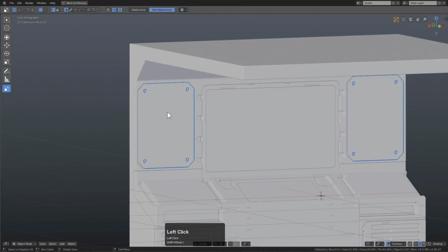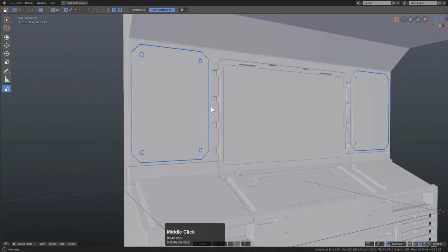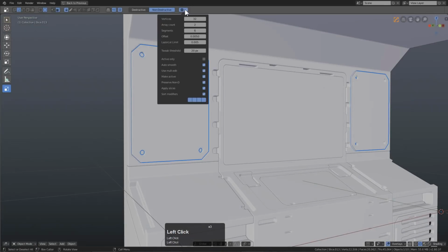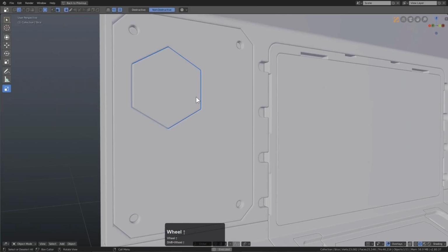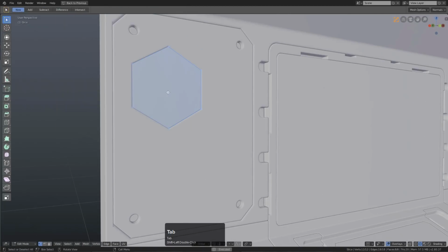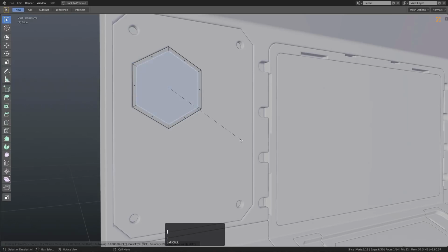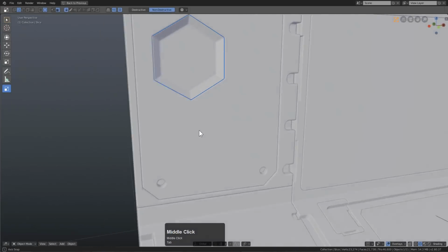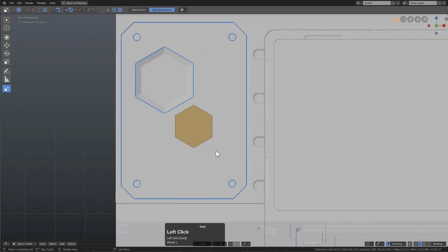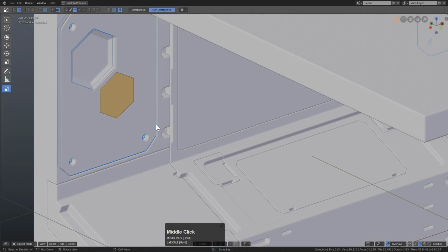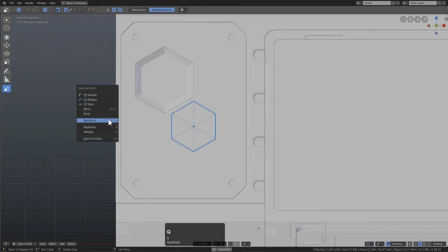Let me show you an interesting trick I've been doing with circle lately. We go to circle, change it to slice, give this 6 rounds, and let's just slice. I love cutting octagons. I'll tap into edit mode, press 3 to go to face, press I to inset, Alt S to push, and that's our first octagon. We look at this from the front and draw another octagon because we never learn. We'll hold shift because this one's questionable. I'm going to clean the mesh because I just don't like seeing that point in the center.